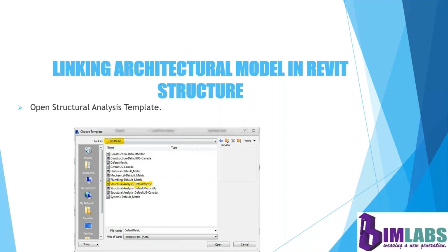So as I said, some of you might be using the Revit software. In this, these are the different templates available. When you work with the architecture model, you take the default metric template. But while working with structural BIM, you have to take the template Structural Analysis default metric. So that template is used.